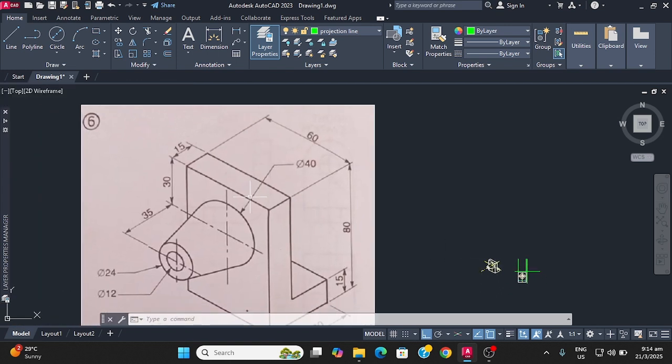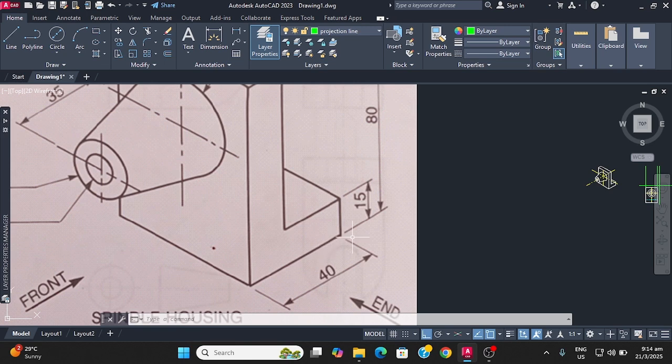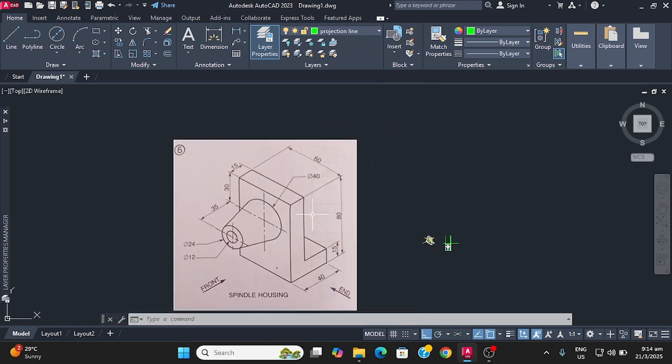So if you're looking down on this object, you're going to be seeing the front part here protrude before we actually see this top part and then the part below here. So let's look at the distance between the front of the object to here, which is 35, and then this measurement across here is 15, and then at the back here it would be 25. Seeing that the entire length here is 40 and 15 is taken out, we have 25 remaining.